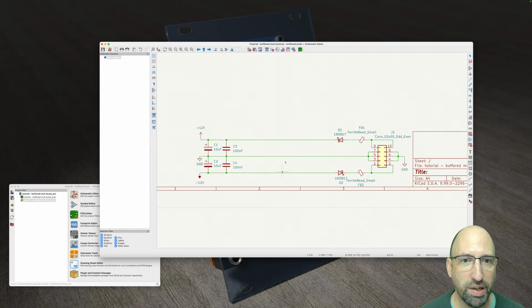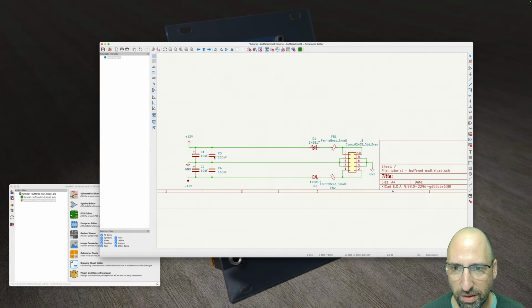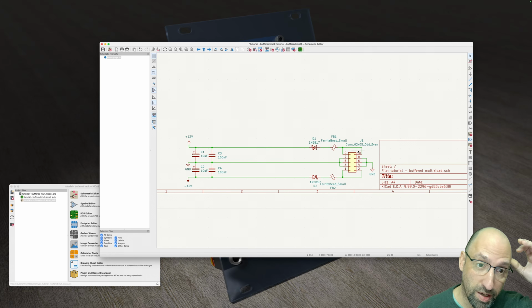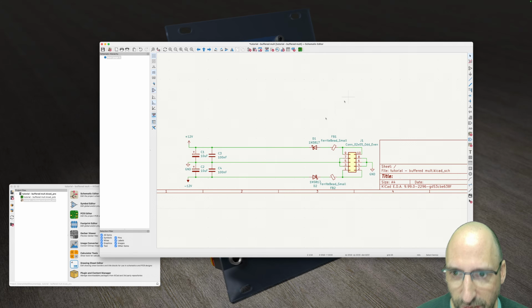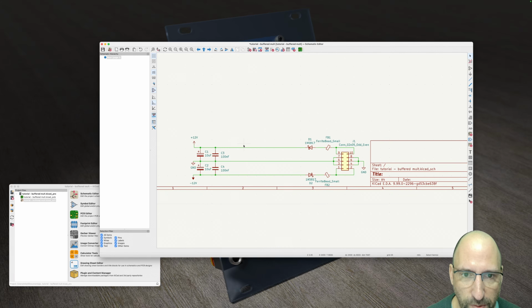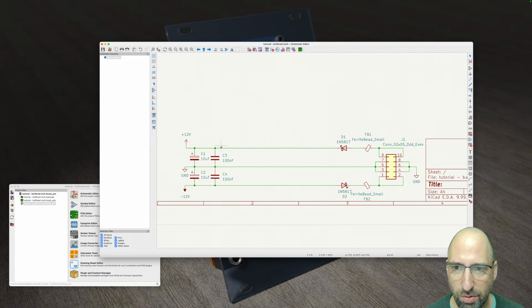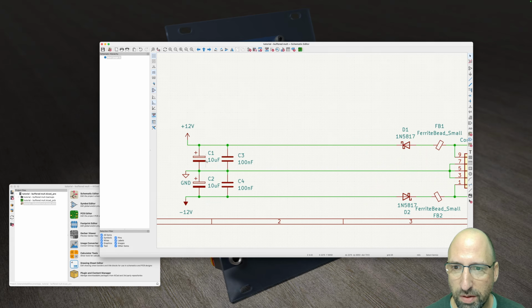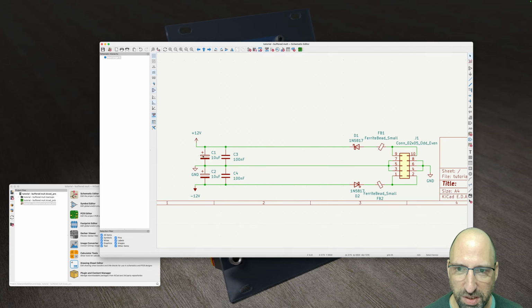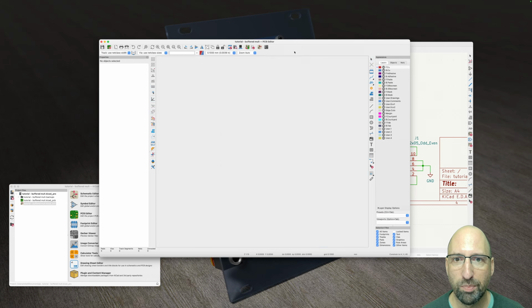This we're probably going to use in a little bit to add in bypass caps for some of the integrated circuits or chips, microchips that we're going to add to this board. Okay, so this little piece is going to give us power, and that's quite nice. All right, so over here, of course, what we've got are just symbols on a schematic, and we're ultimately going to want to link this into a PCB.